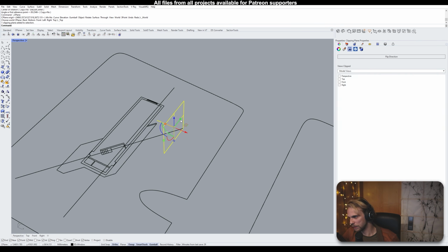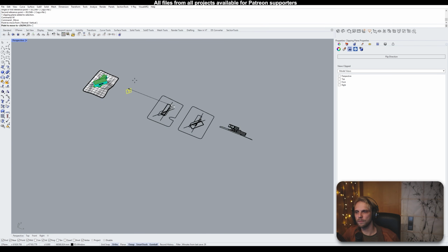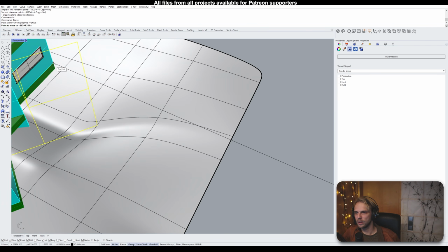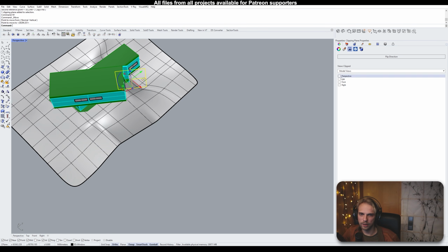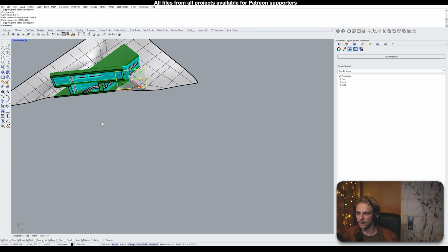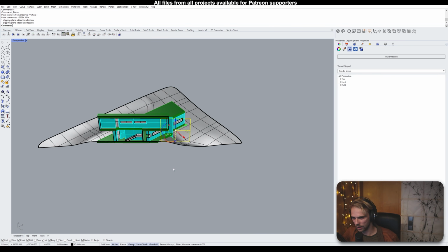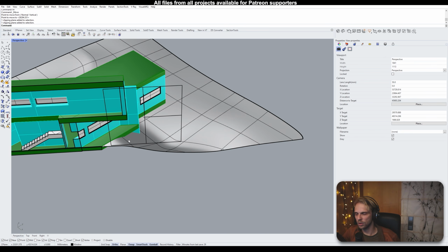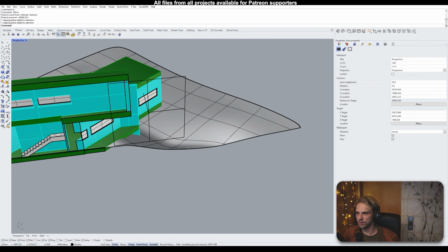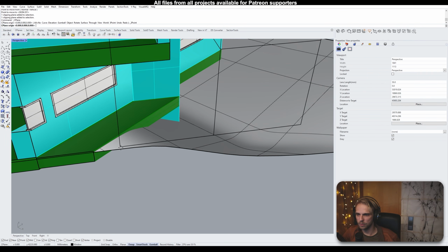Okay, now as you're back to normal with the clipping plane, we can just rotate around this point and we just align it. Just like that. And as per usual, we move it from corner to corner to the correct position and make it start cutting again, like that. Now we will be creating the C-plane again. So 3-point C-plane, as per usual, bottom left.